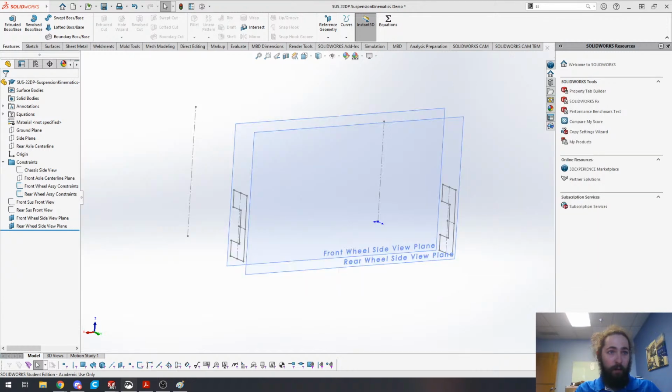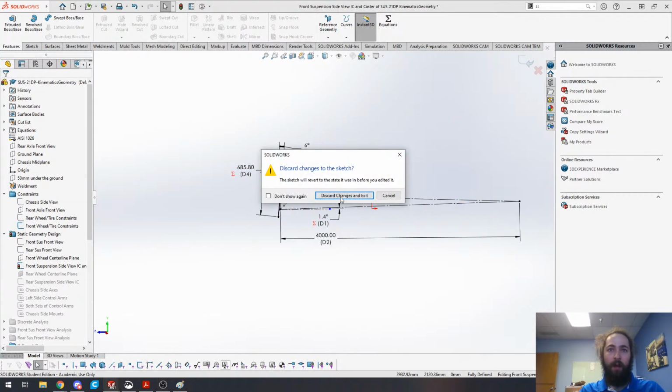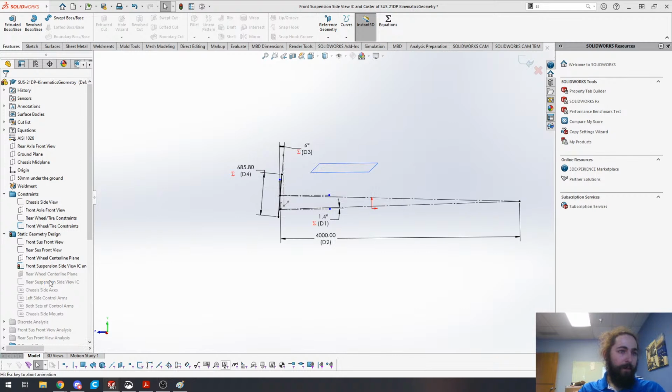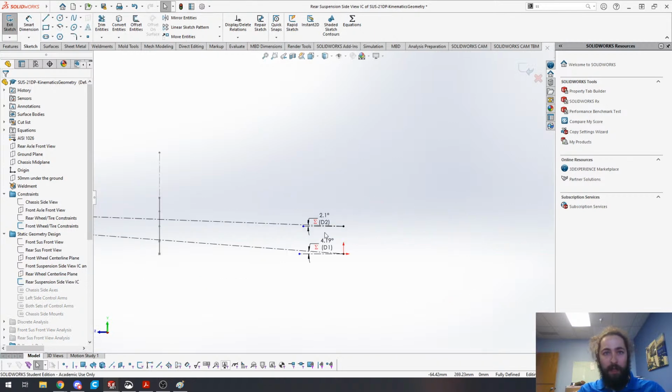Let's see if I can pull up my old notes here. Yeah, so anti-lift in the front only applies to front wheel drive cars. So that's why, if we go back to this sketch here, the rear wheel would be a better sketch to show. So in this case, we have 2 angles. These are driven by our anti-squat and anti-lift.